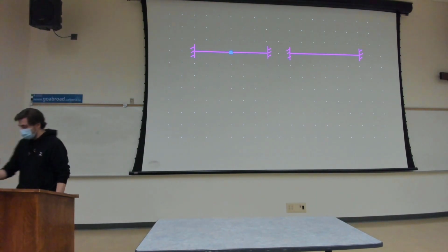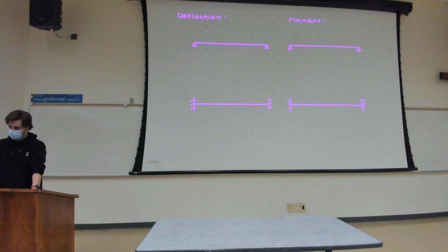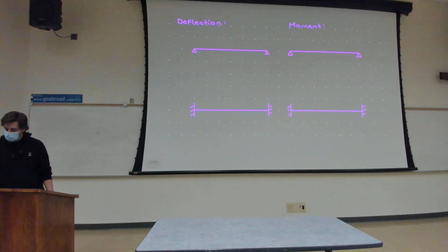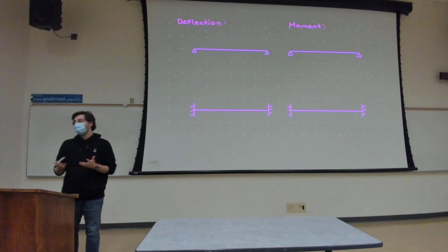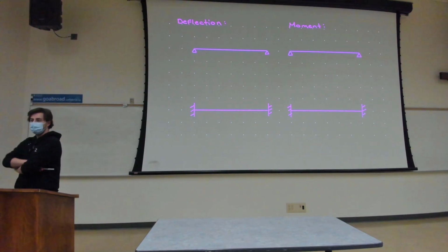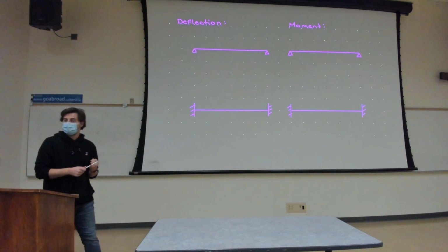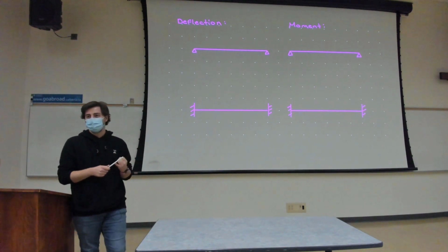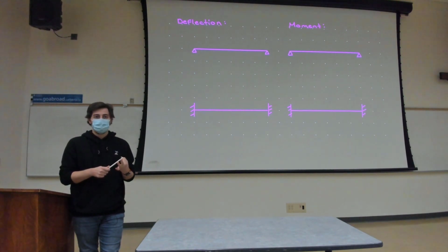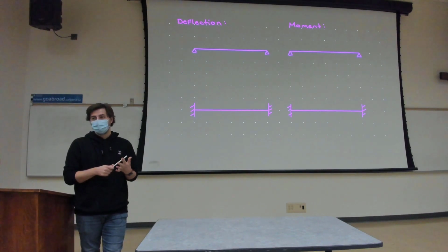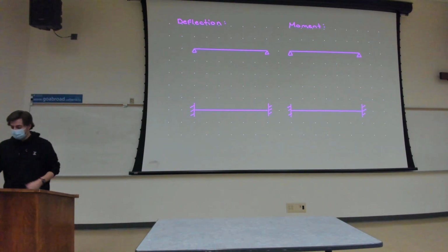We're just going to go through these 2 examples really quick because they are going to appear a lot more. When we deal with beams, we need 4 boundary conditions. The most obvious one is just a support in general. If I have a roller, what's the deflection at a roller? 0. How about a pin? Fixed end? A spring? No one likes springs, so don't worry, I won't give you a spring question.